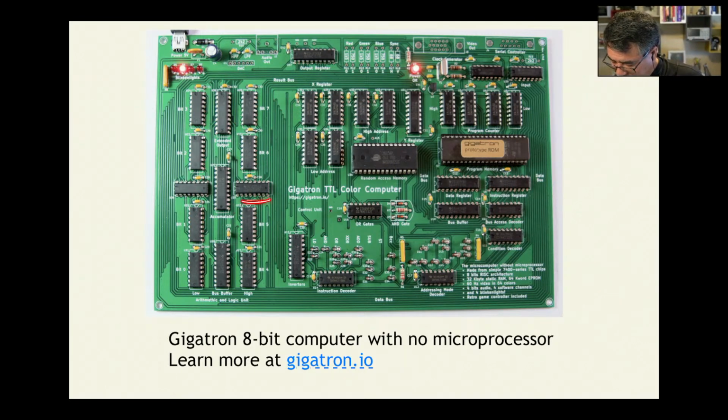Right over here are the adder circuits. This is called the bus buffer, so it loads data in from RAM or ROM and temporarily holds it in a register until it's able to decode it. And then right here is the address decoder. In fact, these little components right here, their job is to figure out what instruction is actually being executed.